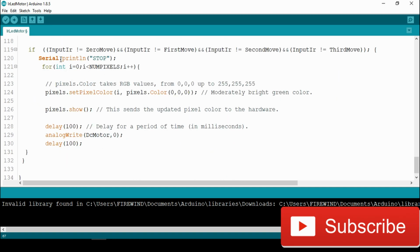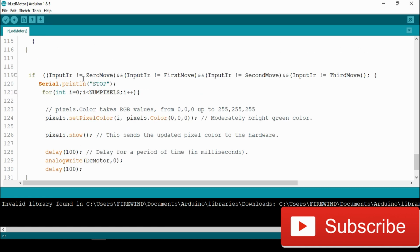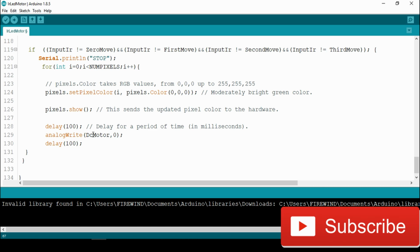At the end, I'm just taking the case where our input is not button 0, button 1, button 2, or button 3. I'm writing at the serial monitor stop, and I'm also writing at our DC motor a 0 value, so our DC motor doesn't move when we are pressing another button.